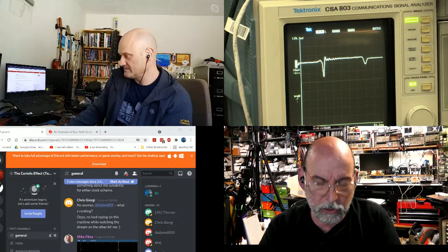And this is like 60 bucks USD, 60, 80. I don't want to guess. My memory blows these days. It was under 100 bucks to do what I can't build myself without doing all this. So I love this. You can get a scope and a pulse generator, and it's the bandwidth of your scope and the rise time of your pulse that will set how much acuity you have looking at these reflections.